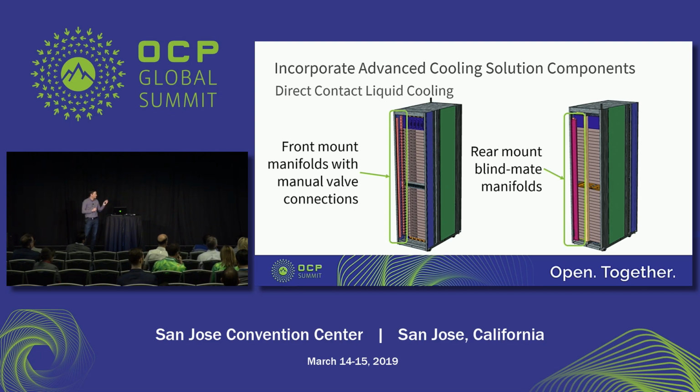So there's both a hot and a cold kind of buried up into where we would normally keep data cables. Those are basically manual interconnects where you can connect the manifold directly to the IT gear, and then when you need to service it, you just manually disconnect it, pull the IT gear out, put in the new IT gear, and then manually reconnect those.